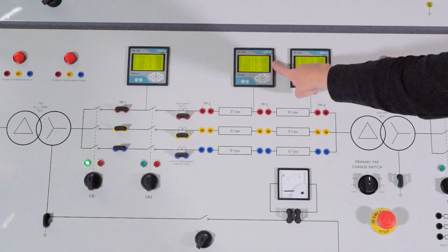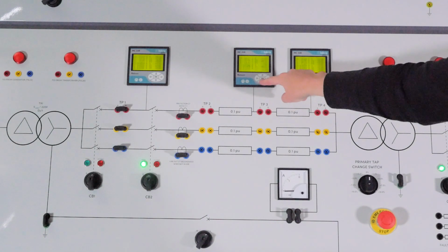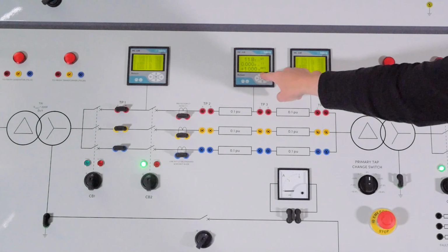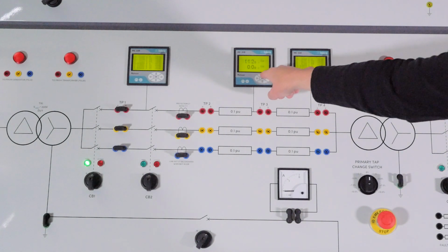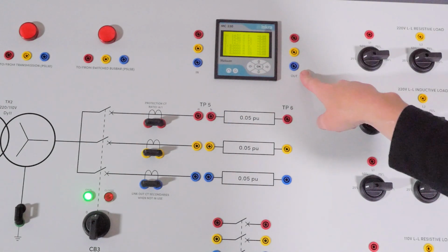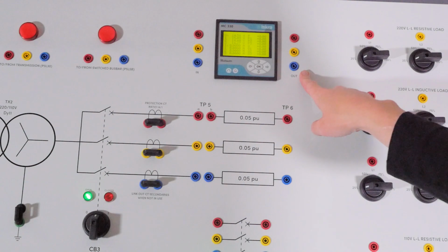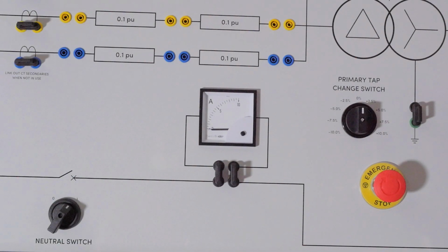The front panel of each meter contains a liquid crystal display and push buttons for navigating the menu. The menus allow the meter to show either a small quantity of measurements with a large display or a large number with a small display. The meter for the low voltage section of the line after the distribution transformer has a floating bus bar that enables the meter to be inserted into the circuit wherever needed. A 10 amp ammeter is provided to measure neutral current.